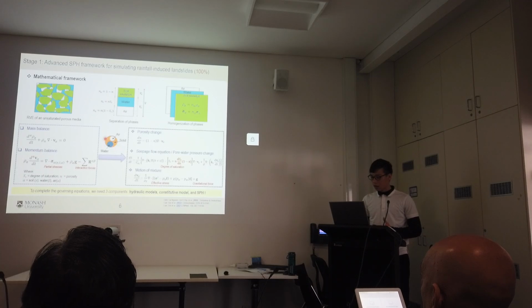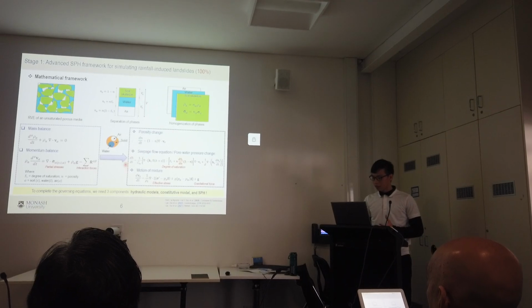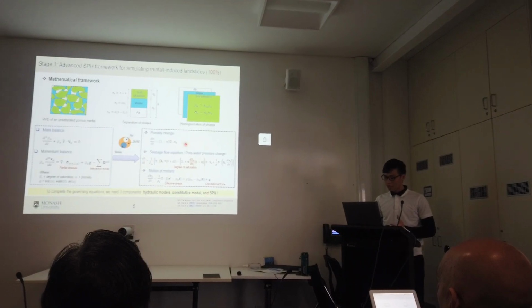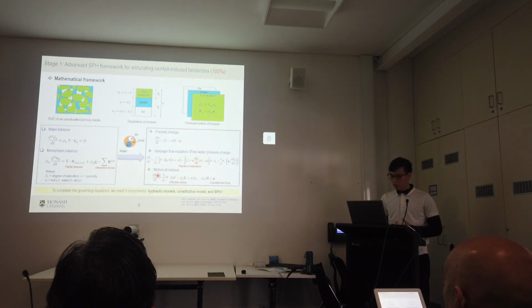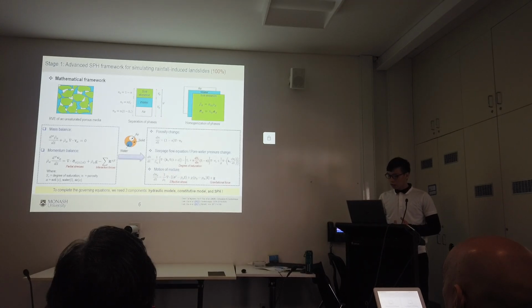Now we use the single-layer approach, where we combine all governing equations to establish a unique governing equation for the entire system, consisting of porosity change, seepage flow, and the motion equation. To complete this governing equation, we need three things: a hydraulic model, a constitutive model, and numerical methods.